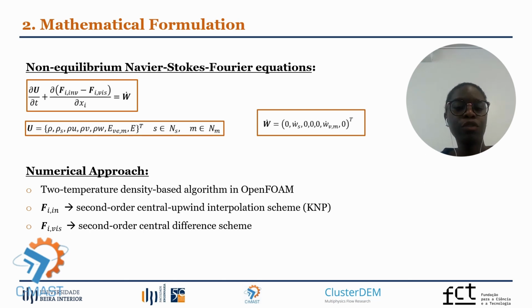During the expansion of the flow through the nozzle, the translational and rotational energies drop abruptly, while the vibrational and electronic energies remain high, at a temperature close to the nozzle reservoir temperature. This non-equilibrium state could prevail through the nozzle and change the quality of the flow at the test chamber.